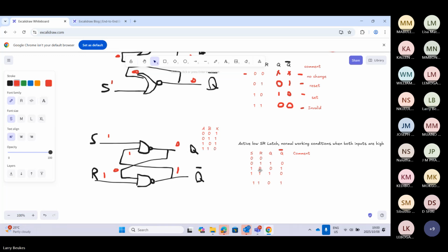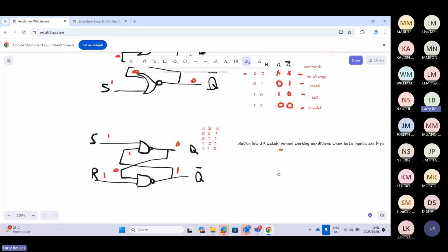Do you see that? It doesn't change. If before we change the inputs, this light was off and this one was on, for example, let's say the green one was off, then the red one was on. Even when we change this input to 1, 1, right, it will still remain the same. So that's why we say no change. So for this, I'm just gonna put don't cares, double X's here. Call them don't cares. You don't care.